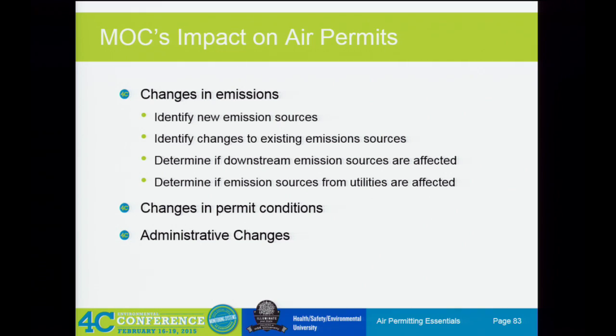Very good. I always recommend that the MOC is not approved until after you have obtained your air permit, because that way the change doesn't occur before you've received your construction permit, and that construction permit is required before you can begin construction. And I think that was the first time I've heard it from somebody that says there's an initial sign-off that says, yeah, we can do this project, but not until we have our air permit. I think that's also a very good step to have. That allows your process group to go on with the project and developing the details of that project while you go and obtain your air permit.